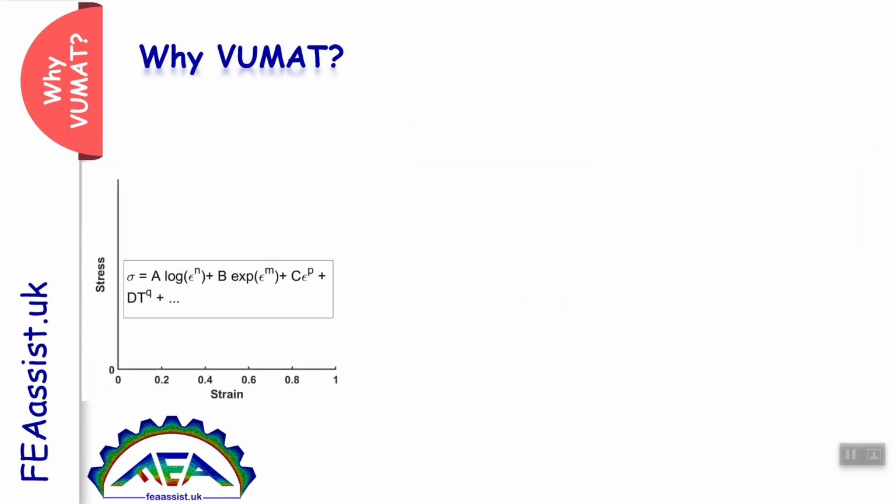But what if you have a new equation for a new material, a new constitutive equation, and the equation is not included in Abaqus to enter the parameters and constants? Then you will need a place to write your equations and force Abaqus to solve the problem based on your equations. This place is the VUmat subroutine.